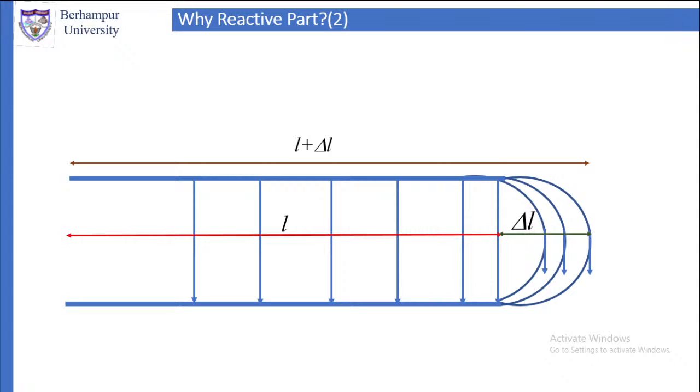So it will be L plus delta L. This delta L we have not taken care of when we designed the antenna. Because of this delta L, there will be problems. The problem that we have seen, the frequency is not 920, but it has come down because the length is more. So the electrical length is more than lambda by 2, and so the frequency has come down.